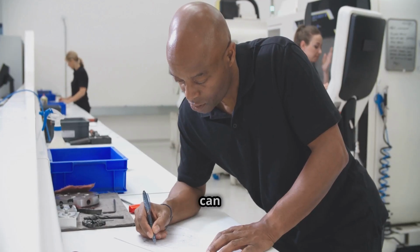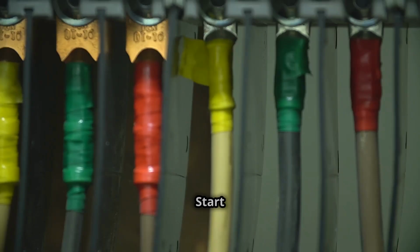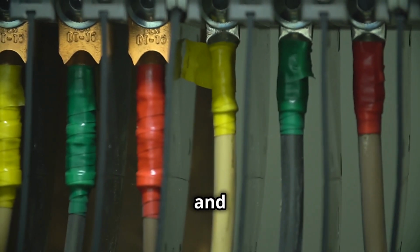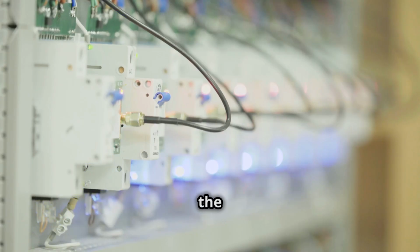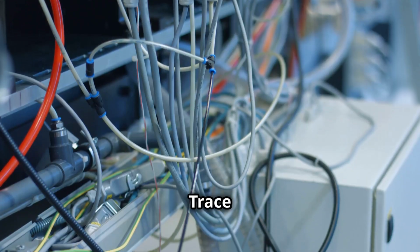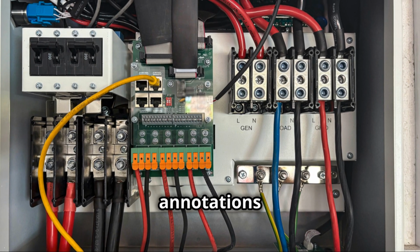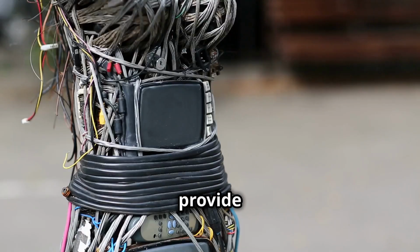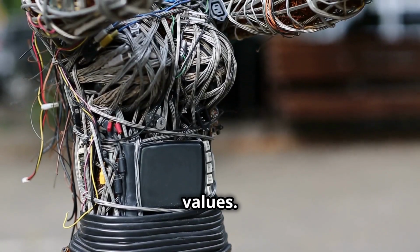Reading wiring diagrams can seem daunting at first, but with practice, it becomes easier. Start by identifying the power source and follow the flow of electricity through the circuit. Pay close attention to the symbols and their meanings. Refer to a symbol legend if needed. Trace the wires to see how components are interconnected. Look for labels and annotations on the diagram. They provide additional information about the circuit, such as voltage levels, wire gauges, and component values.